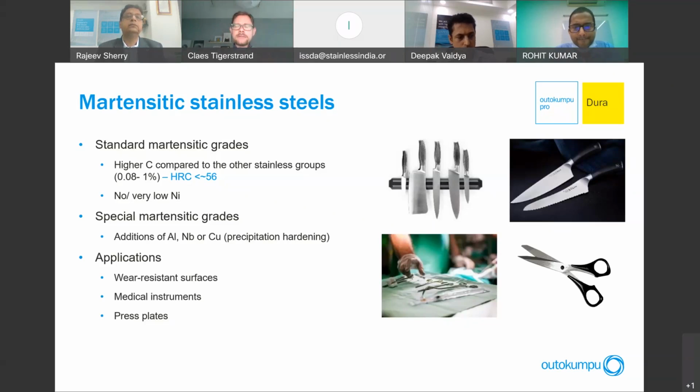No, there you need to be careful. If you have carbon steel contamination of a stainless steel surface, of course, that is negative, and that can actually affect the corrosion resistance, so that locally you can have pitting corrosion where you have that contamination.